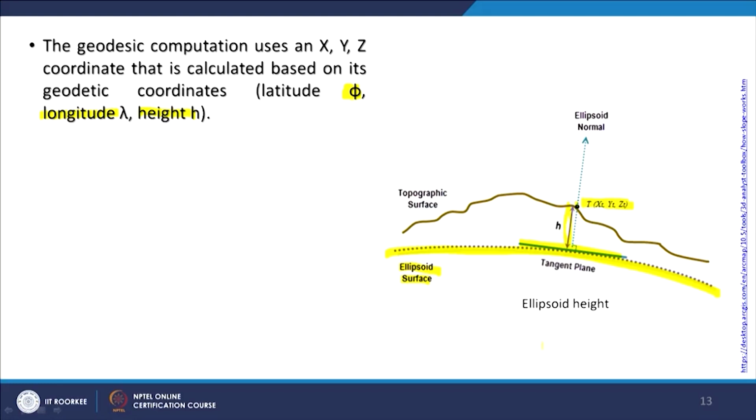If it is coming from the Earth center, then definitely it would be the ellipsoid normal, otherwise not. That is why in GNSS you get variations; you expect something but may not get an accurate elevation value. Though for XY, that is in the 2D system, that issue is not there. Generally, the coordinates in GNSS systems you get very accurately.